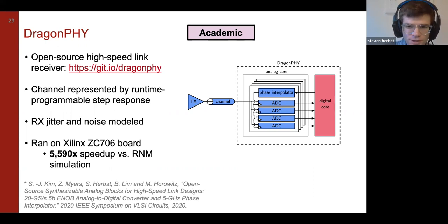So I think that was the first question about how long does it take. The other question about the size of the chips, I think there is definitely a limitation when using FPGA boards that the largest FPGAs have perhaps 1 million, or maybe a few million lookup tables on them, which is not enough to emulate very large chip designs. It's enough for small commercial designs. So I think another future direction would be looking at using these synthesizable models in a commercial emulator context where those systems have the capacity to emulate a full chip design.